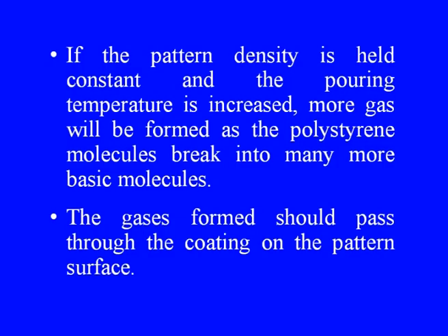If the pattern density is increased, then at a constant pouring temperature, more gas is formed. If the pattern density is held constant and the pouring temperature is increased, more gas will be formed as the polystyrene molecules break into many more basic molecules.